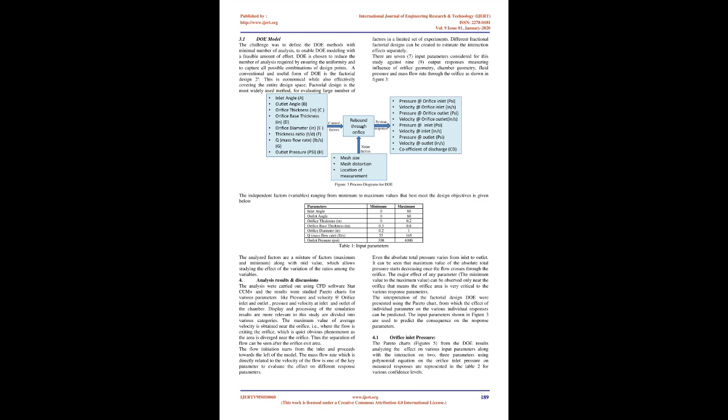For surface mesh, STAR-CCM+ has 2 models, i.e. the surface remesher and the surface wrapper. The surface remesher improves the overall quality of the existing surface of the volume mesh models. The surface wrapper is typically used in concurrence with the surface remesher. However, as the surface wrapper makes available a manifold mesh from a complex geometry, it is not used in the model described in this paper.